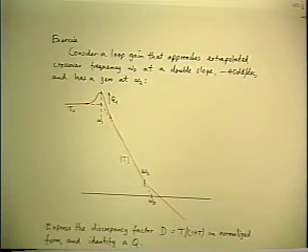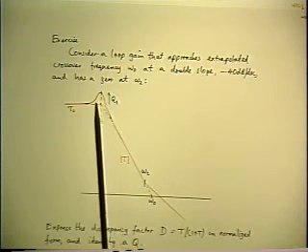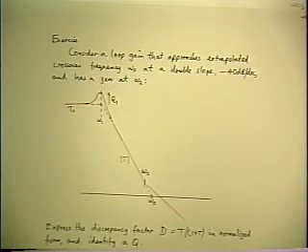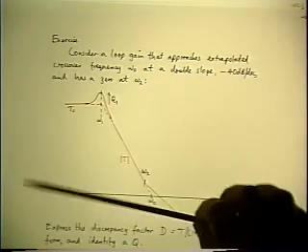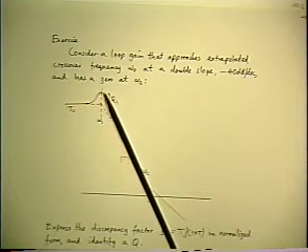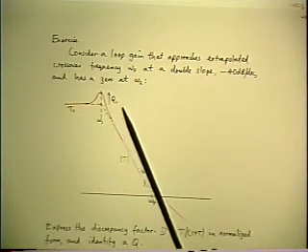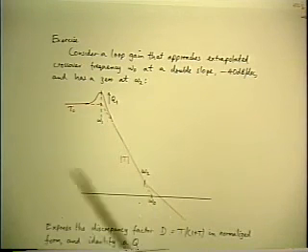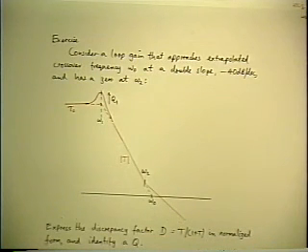If you don't do anything else to do with frequency compensation, then the loop gain would consist simply of this second order two-pole filter, which means that when you close the loop, you're going to cross over on a double slope, the skirt of the LC filter, and you wouldn't have any phase margin. So you'd be on the verge of instability before you've done anything else at all.